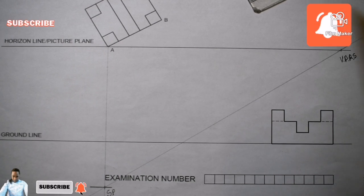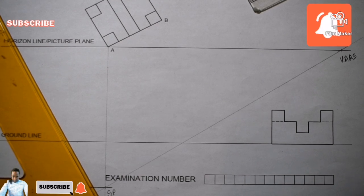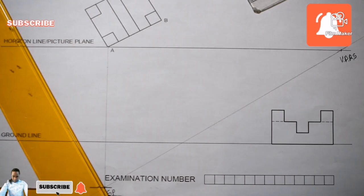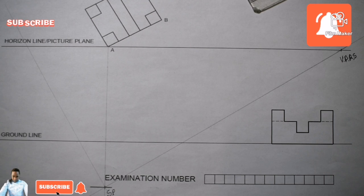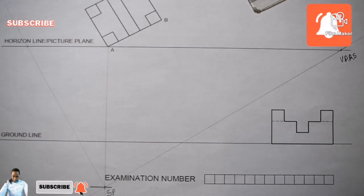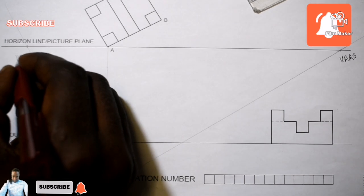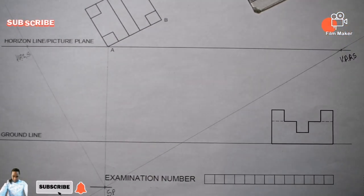Vanishing point of my right hand side. You understand? So again, I take this point SP at an angle of 60 degrees in a clockwise direction. Once it touches this line of the picture plane, the horizontal line, I have a point right there. That one I'll name the vanishing point of my left hand side.